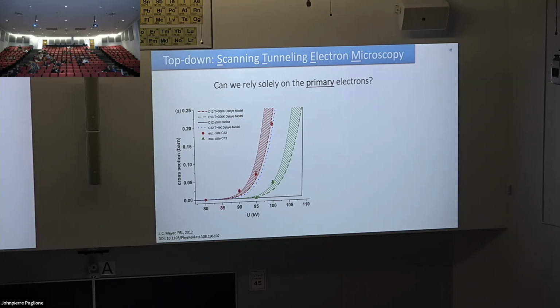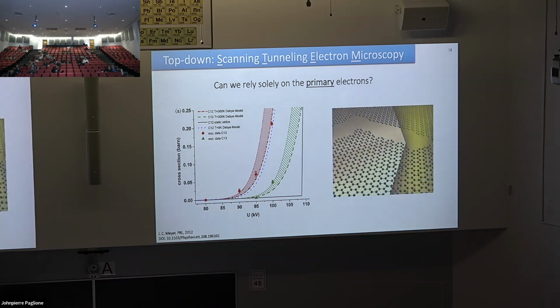You can see as you're reaching 90 to 100 kilovolts acceleration for your electrons, suddenly a feasible process is that you are carving atoms out of your graphene. So instead of using this technique for imaging, maybe we can just brute force knock out atoms, pattern or sculpt directly with the E-beam. This is, as you can imagine, a very slow process, but then we are not limited by some secondary electron scattering. We are just limited in spot size by the spot size of the E-beam itself.